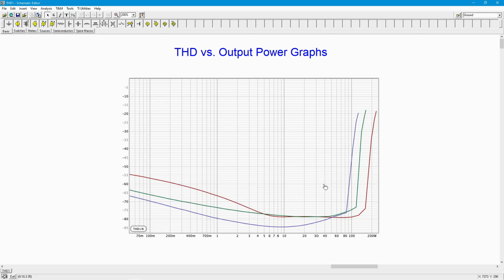Use your brain. Think about this for a sec. If you were listening to music in your home, at a fairly loud level, let's say 80, maybe 85 dB SPL, that's pretty loud. If somebody comes in, they're going to have to talk really loud to have a conversation with you. If the distortion is minus 60 dB, 0.1%, that means in your room it's sitting at 60 dB less. So if the average SPL is 80, 85, the distortion is sitting at around 20, 25 dB SPL.